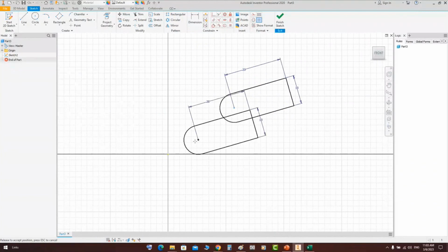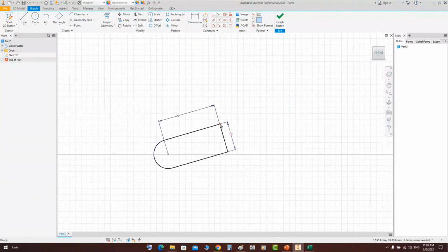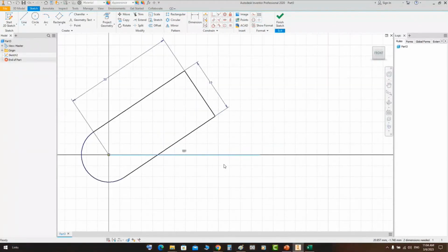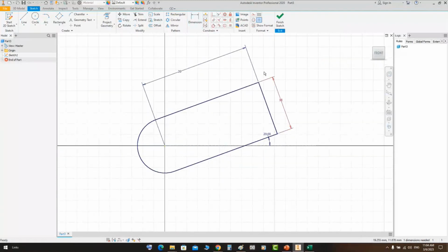So now this sketch, if you move it here, now you will be able to fix it. And if you wanted to define an angle, let's draw a construction line. We draw a horizontal line, and let's convert it to a construction line. Now you will be able to define the tilting angle of this one, and you can see that this sketch becomes fully constrained. Okay, because if you try to move this sketch now, it will not move, because all constraints make it a fixed sketch.